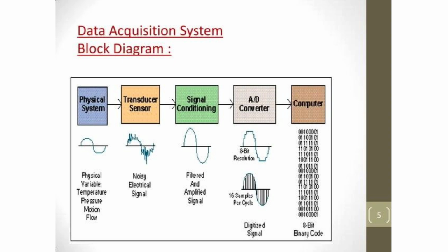Looking at the schematic block diagram, the components you can see are the sensors or transducers, which interface with the physical medium to translate parameters like temperature or force into a proportional electrical signal. Second, you can see the signal conditioning, which cleans, amplifies and pre-processes the raw noisy electrical outputs coming from our sensor.